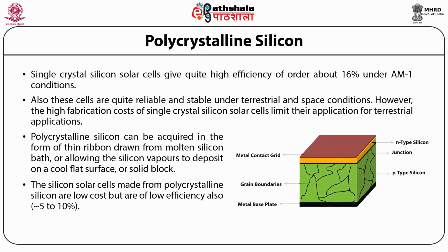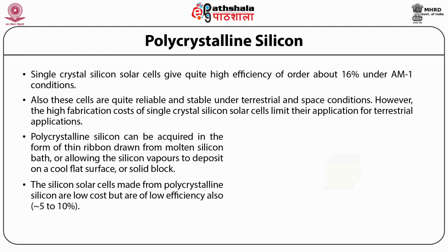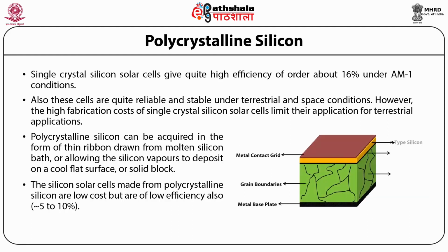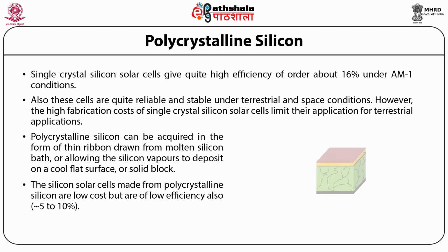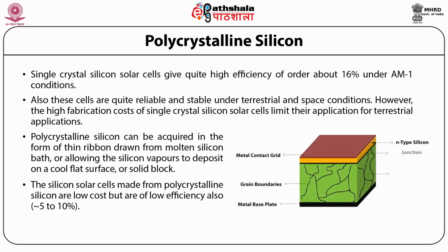By inserting a very thin insulating layer between the metal and the semiconductor, this problem can be solved, and the solar cell is named the metal insulator semiconductor solar cell. By making the insulating layer very thin, VOC can be increased and can become almost equal to the p-n junction cells.